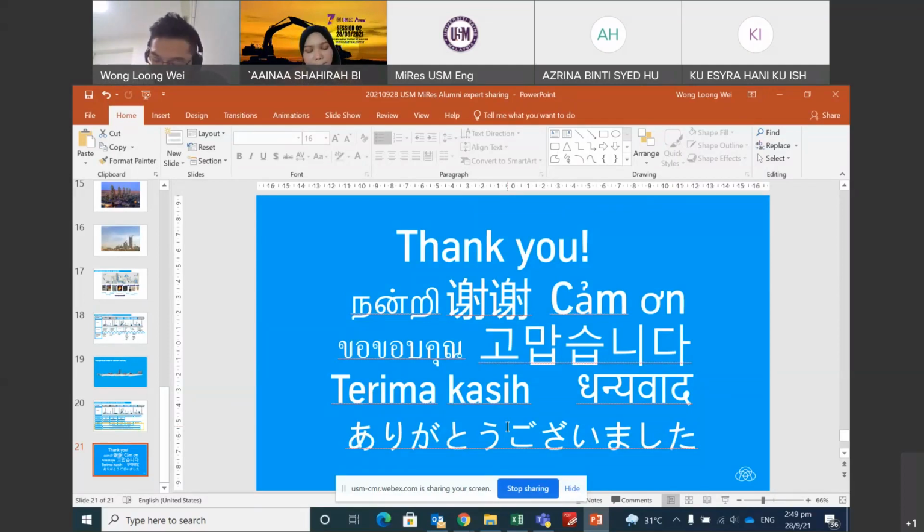So, the first purpose of the grinding aids is of course to support or to ease the process of grinding. For a ball mill, during the grinding process, the balls inside the mill will have some electricity. This will cause the powder to stick on the ball or on the wall. The grinding aid is to avoid the raw material from sticking on the grinding media and sticking together.